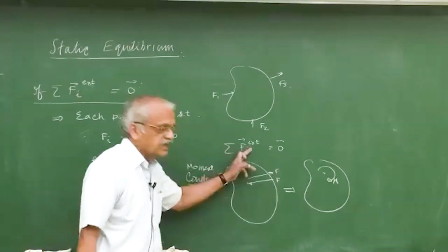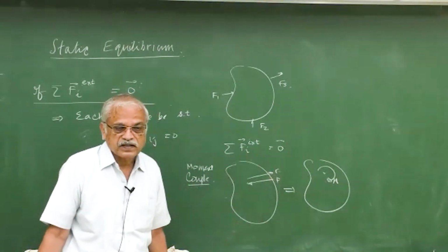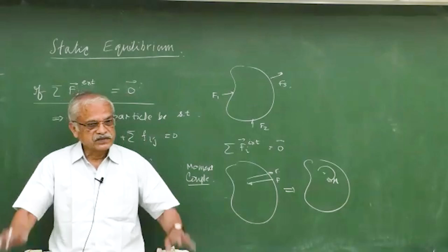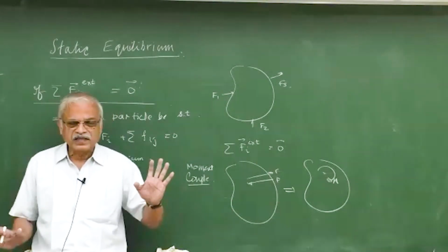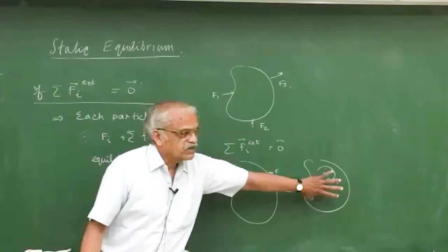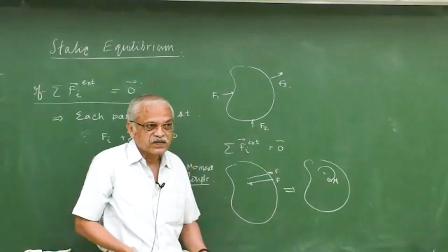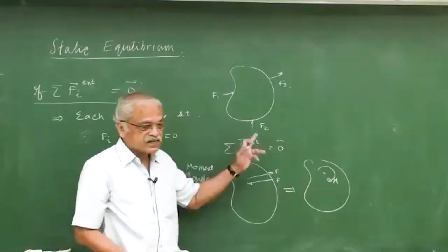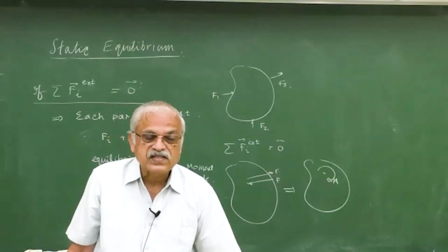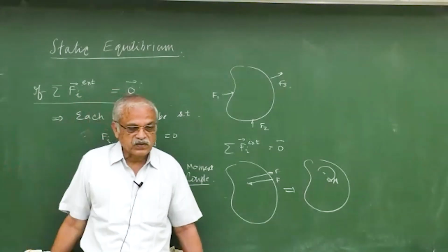So this equation is satisfied, obviously, since sigma Fi is 0 because the forces are equal and opposite, so their vector sum is 0. Uniform translational motion? No, just think, it is still not in equilibrium. Something is happening here. Rotation, isn't it? If you subject a body to this kind of moment, it is going to rotate. Its translation is arrested by this equation, but rotation is not constrained. It will rotate at the same place.